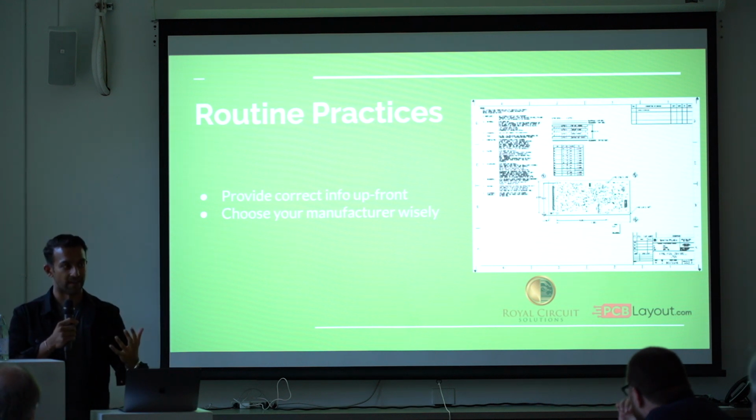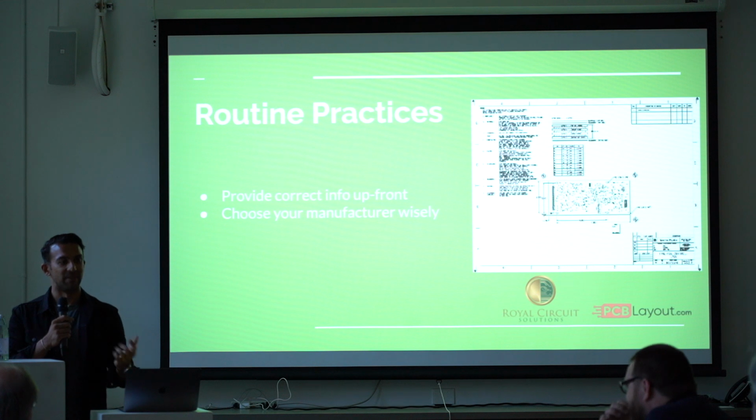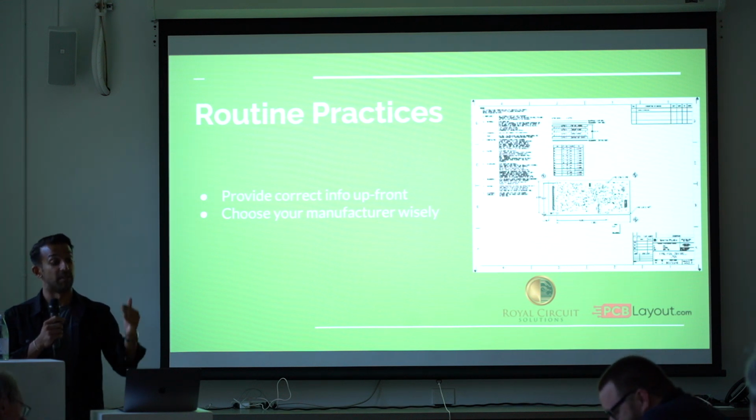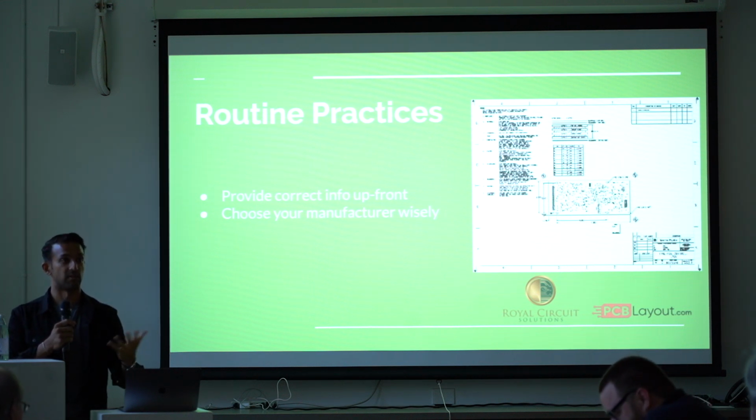I get the board back. It's a rigid board, but it's totally bendable. Like, this is 7 mil thick. How am I going to run LEDs on this thing? What the hell? And then I looked through the fab note, and they were like, yeah, but your fab note said 7 mil thick. I was like, why would I ever do that? But it's just because I copy-pasted. I didn't read the fab note, but the fab house will read everything. So it's a blessing and a curse.